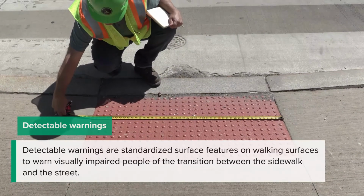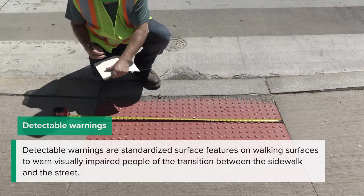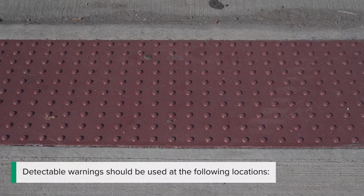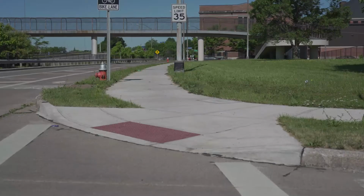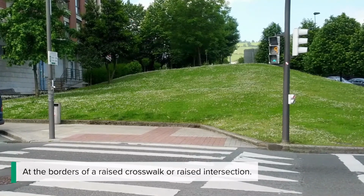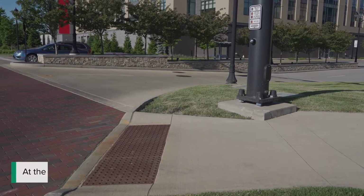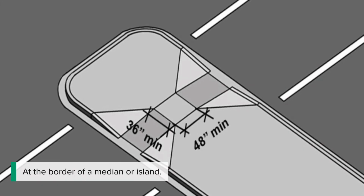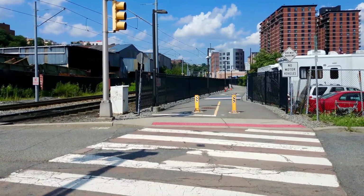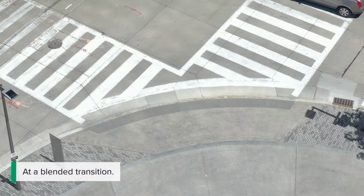Detectable warnings are standardized surface features on walking surfaces to warn visually impaired people of the transition between the sidewalk and the street. Detectable warnings should be used at the following locations: at the edge of a depressed corner, at the borders of a raised crosswalk or raised intersection, at the base of a curb ramp, at the border of a median or island, at a street crossing for a shared use path, where a sidewalk crosses a railroad track, at a blended transition.